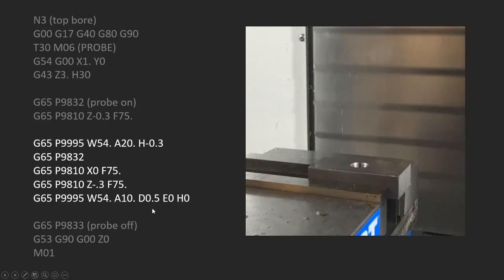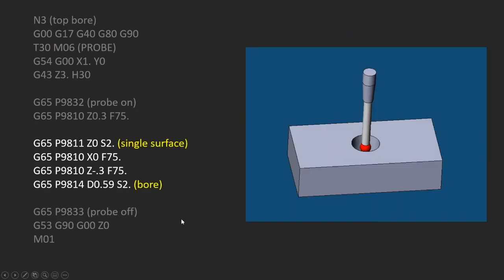So that's what we had in the second webinar, and here's how I'm going to change it. Very similar to the previous example, we still have a single surface. I'm setting G55 here. I don't need to turn the probe back on, just like what we had before. I do my same repositioning, and then I do a bore. Turn the probe off and I'm done. So it gives you a little idea about that.